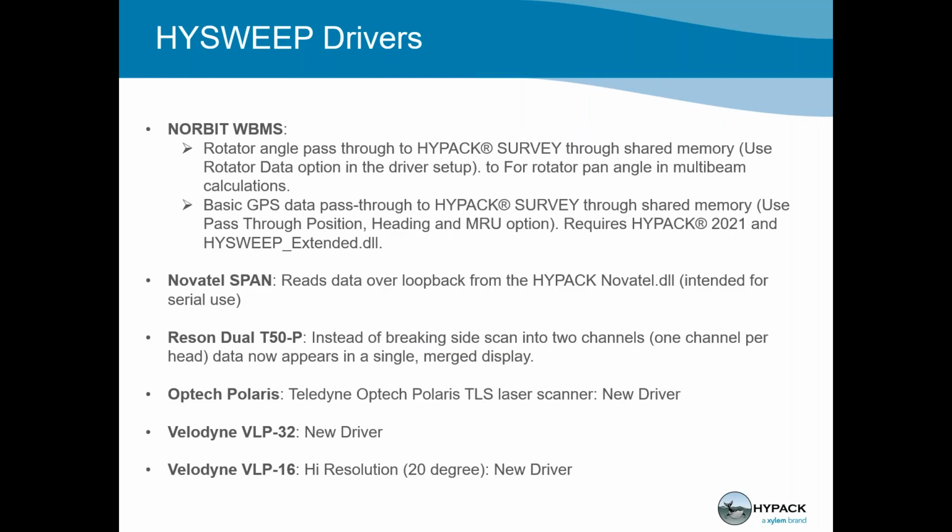For the Norbit WBMS, some of the drivers in HYPACK pass rotator angle information through shared memory. Same with the GPS pass-through. For Novatel SPAN serial users, it'll pass the information over via UDP shared memory so you can use it in HYPACK.